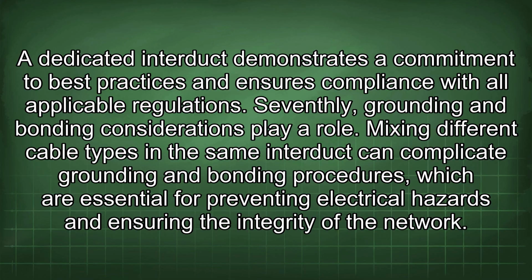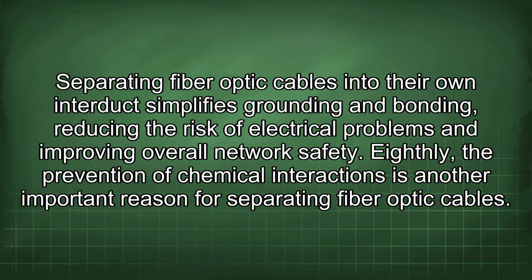Mixing different cable types in the same interduct can complicate grounding and bonding procedures, which are essential for preventing electrical hazards and ensuring the integrity of the network. Separating fiber optic cables into their own interduct simplifies grounding and bonding, reducing the risk of electrical problems and improving overall network safety. Eighthly, the prevention of chemical interactions is another important reason for separating fiber optic cables.